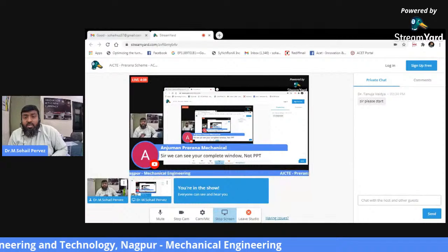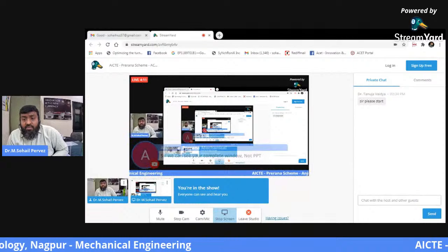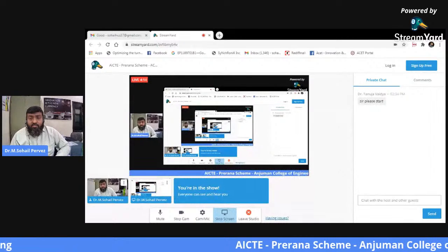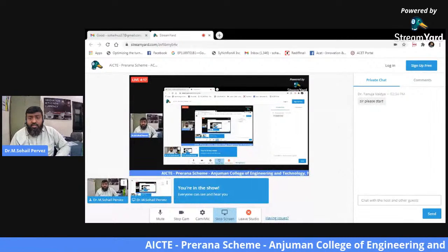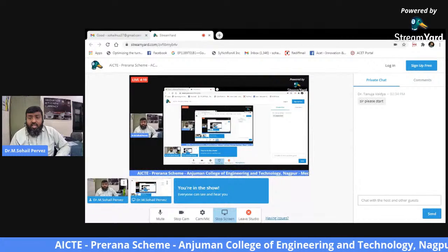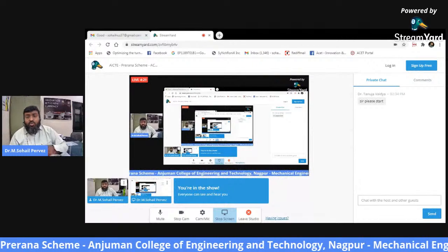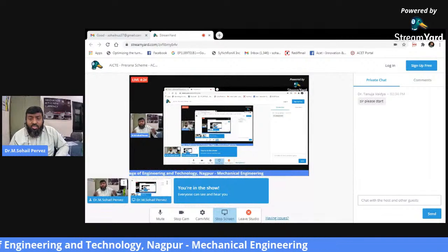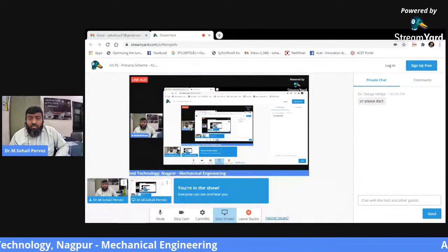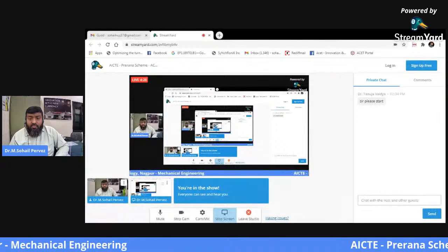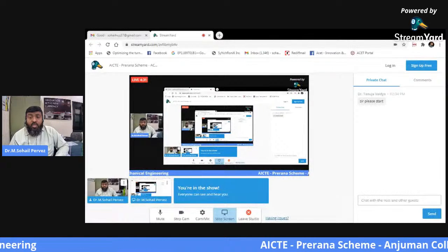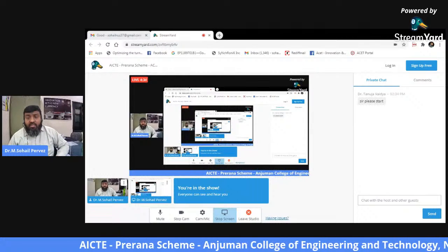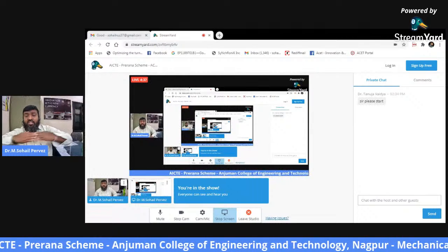Now the third type is a combination of single transverse and double parallel fillet weld. Now look at this particular diagram, wherein this weld, if applied with the transverse loading, then these two, that is L2, this fillet of length L2 will be subjected to shear, and this length L1 will again be subjected to tension.